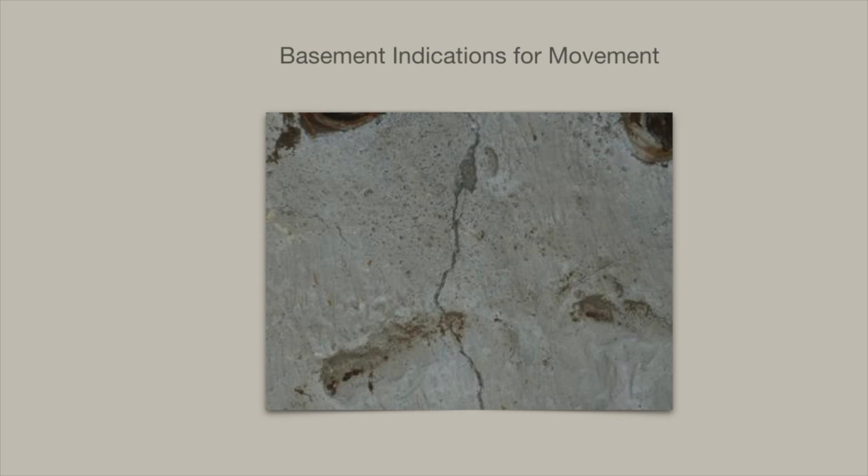Basement indications for movement. The diagrams on the next slides are only a guideline as to why some cracks occur. Never put yourself in the position of stating the reason for these cracks. Always refer your client to an engineer who specializes in residential foundation problems. Foundation cracks can be scary for the inspector. You shouldn't try to determine whether the crack is a structural defect or not. If you are unsure, say so. Don't try to pretend you know it all. That is what will land you in court.